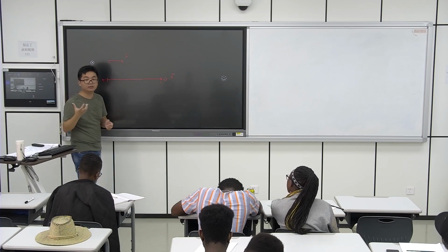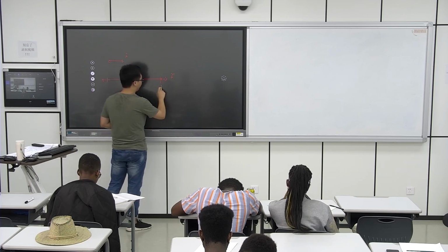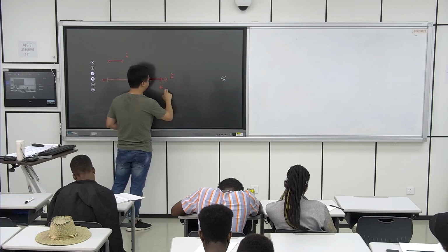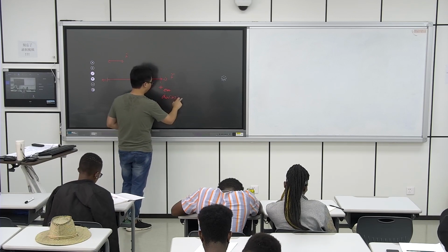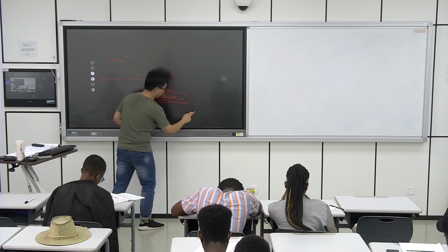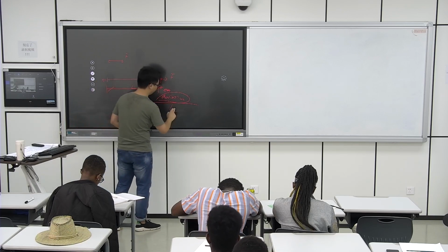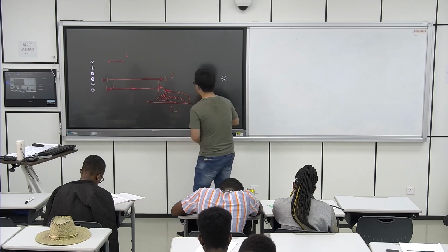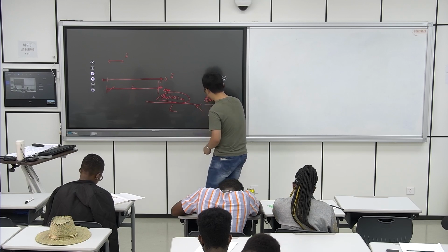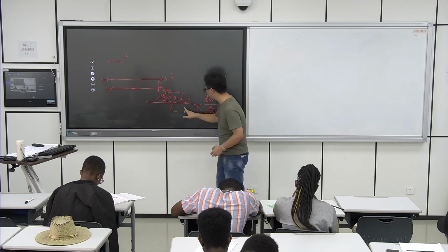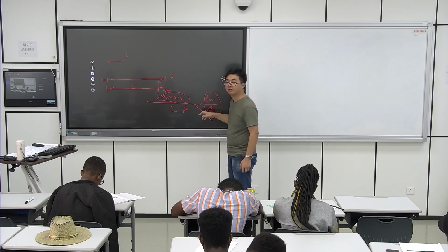Because of the friction, this area causes this deviation. This deviation divided by the total length L is larger for the smaller specimen than the same deviation divided by a larger L. This L is smaller, this is the larger. So this value, of course, will be larger, right?